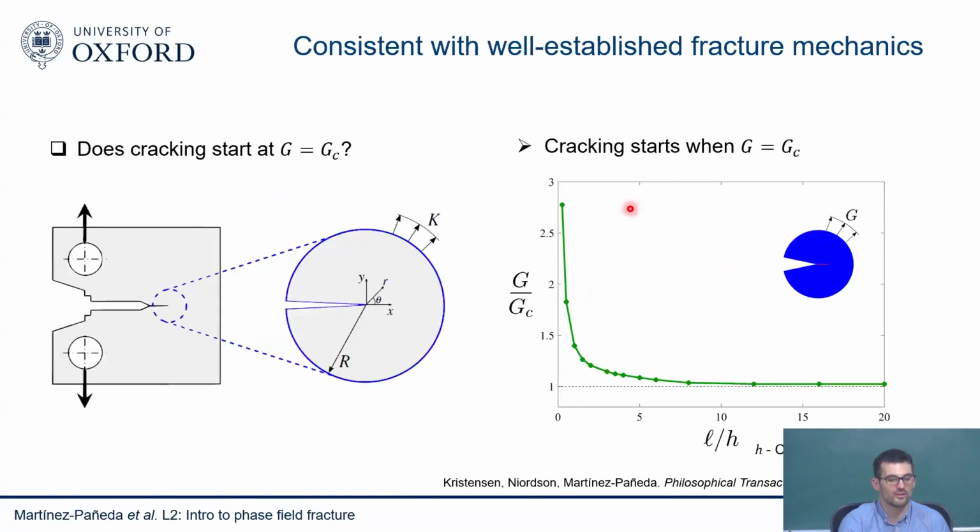And I said, the critical thing that happens here is I do a simulation, I apply a load that I then convert into a K, and then eventually I see that when the crack initiates, my crack just grows because it's a linear elastic material, it's brittle, mode 1, it's just going to grow all the way through.